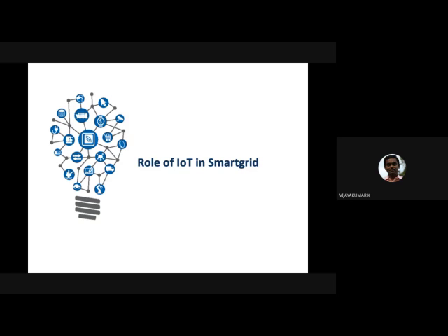So now we have the idea. If you have distributed generation in the smart grid, how does it play in the system? You must understand that now, by looking at the previous material. If it's connected to the loads, then you need voltage and frequency regulation. And if it's connected to the existing grid, then you have to do active and reactive power control.